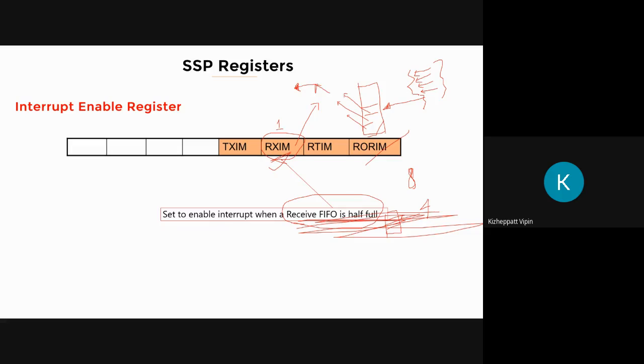Think. Sir, in a multiprocessor system, so not multiprocessor, uniprocessor. No, sir, I'm telling multiprocessors, I mean, more number of processors. Instead of having an interrupt for every bit when it is received on the FIFO, it is better to have 4, and after that there is 1 interrupt for half full. Why is it better? So that it will not stop other tasks whenever there is an interrupt.